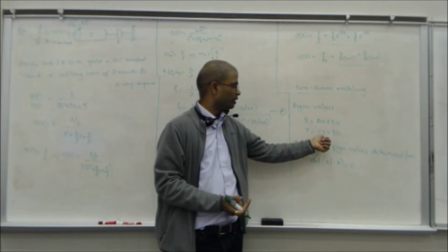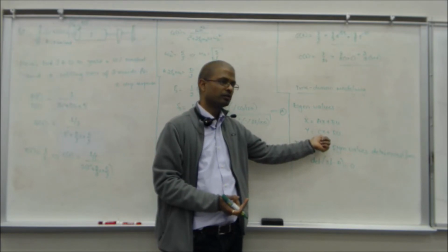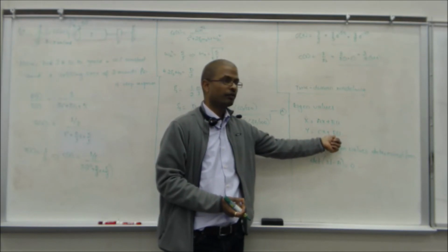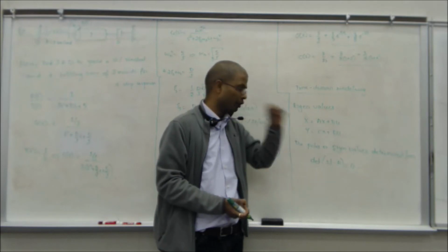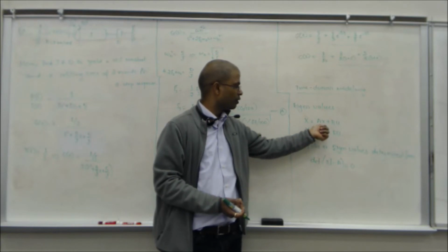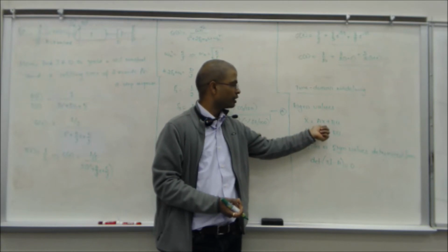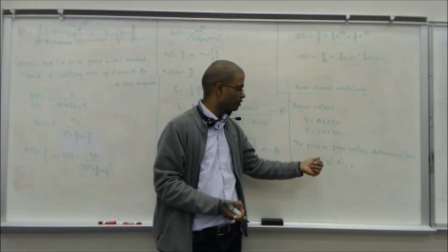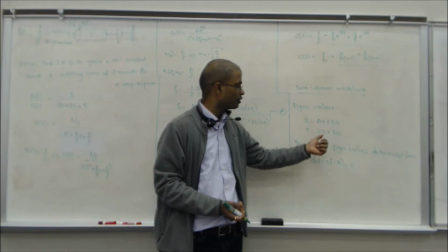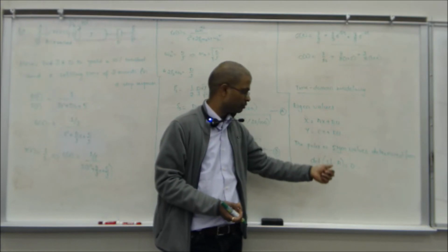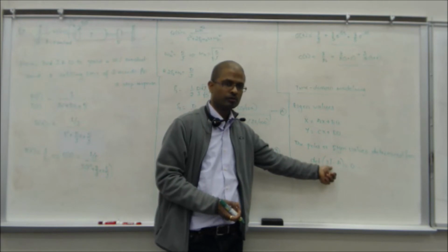This is the output matrix, which affects the control matrix, which affects the output. So they will most certainly have to be in this system matrix. And the values of the eigenvalues which make this determinant equal to 0 would be the poles.